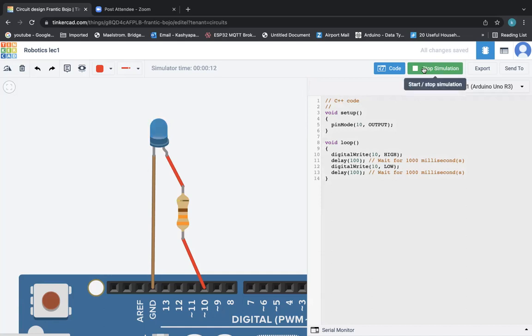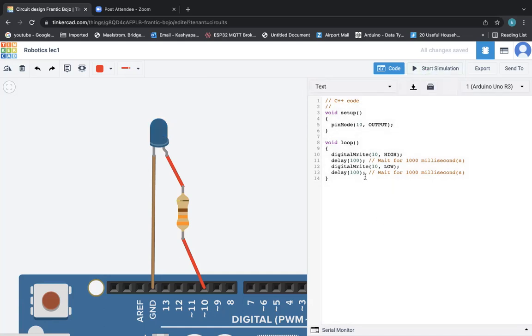Likewise, you can change. And as you asked, how to stop this blinking? There are many ways. One way is to reduce this delay to 1 millisecond. So 1 millisecond is a very small time. So your eyes won't see it switching off.